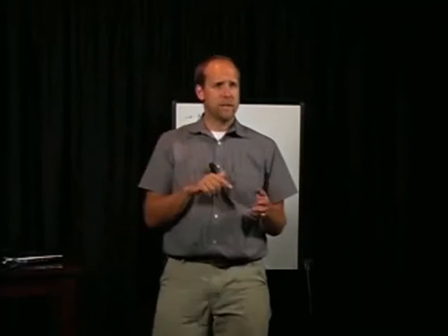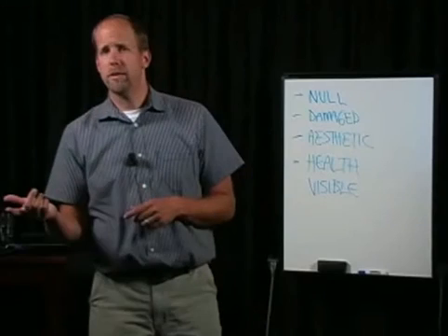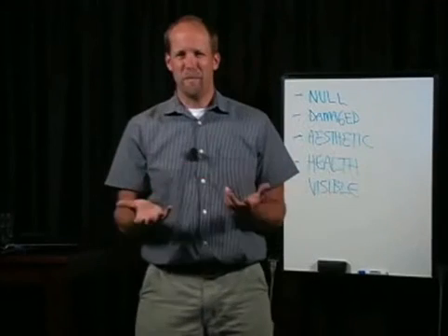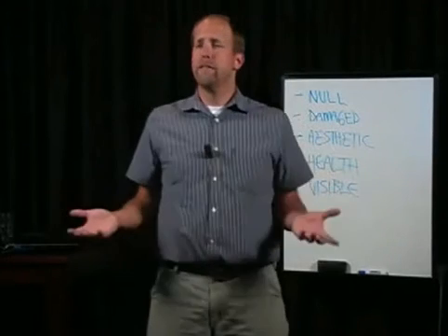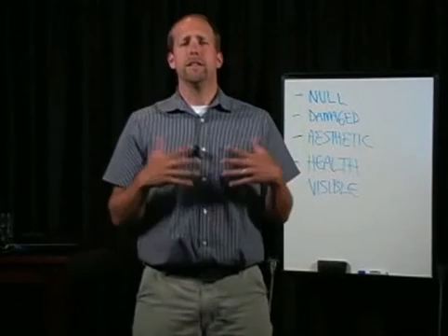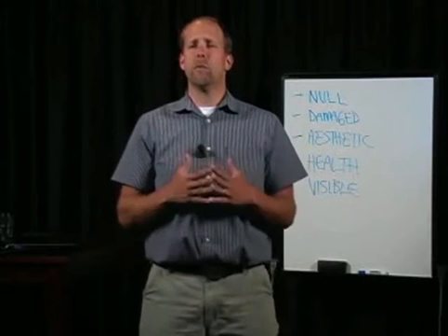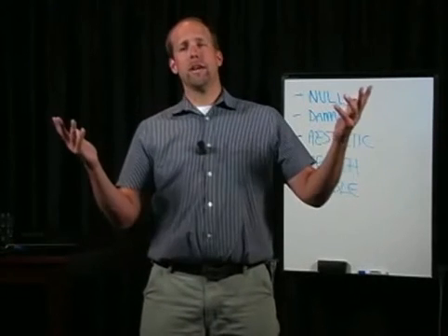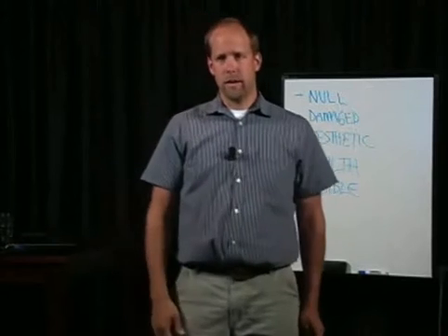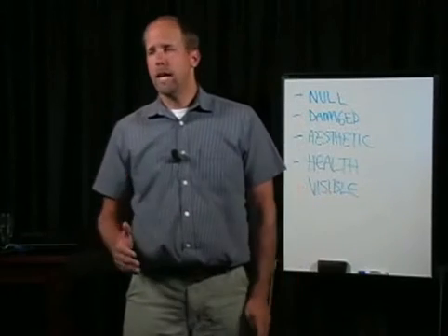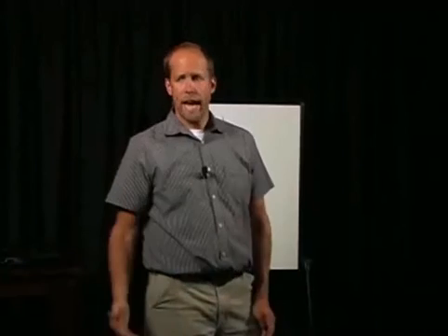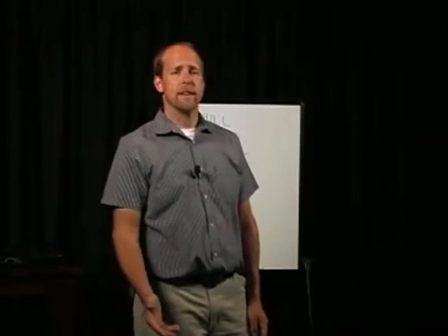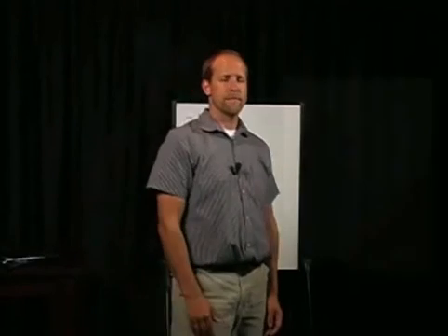Carpet stains may also look like mold. Spider webs, fine dust, paint spray, dried mud, water stains may all give the appearance of mold growth. The inspector who reports the existence of mold growth based upon the discovery of something that appears to look moldy is likely in error. It may be mold, it may not. Error comes with guessing. Don't guess.